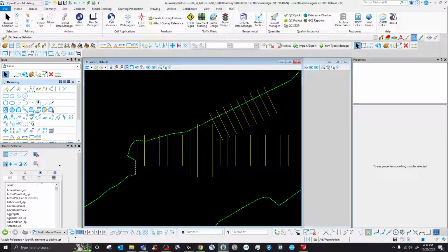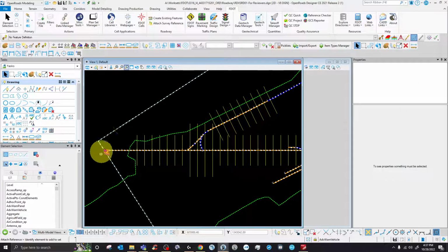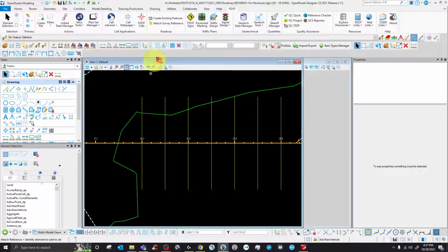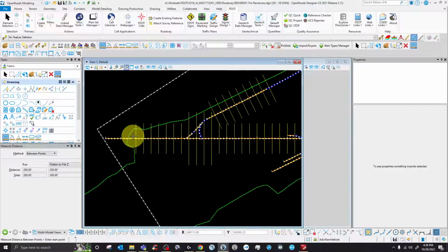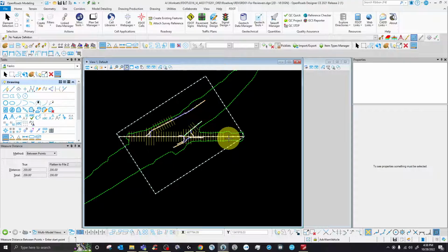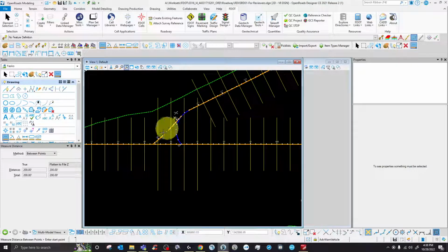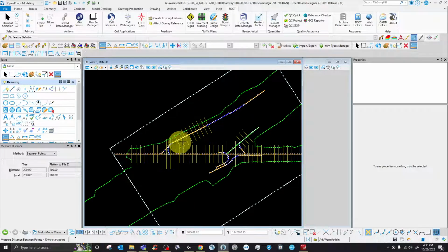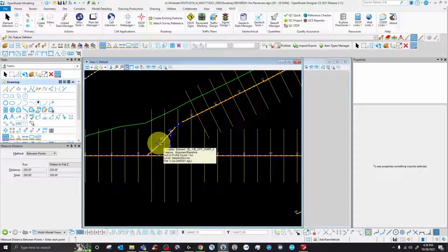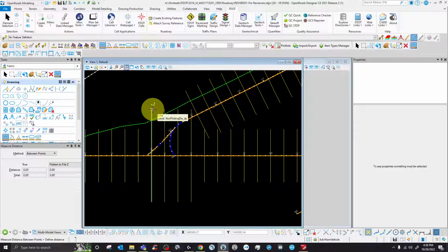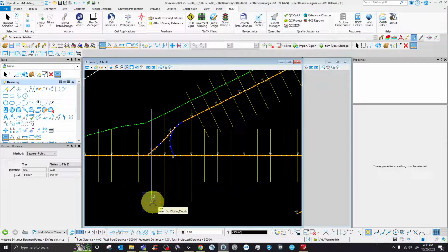So what I was trying to say is I already did this preparation. When I say preparation, I mean I made sure that this is 200 here to cut cross sections, and it's an increment of 50 feet, and I laid it down over the whole thing where we're stopping. Since here we have work for the ramp, I decided, I hope it's gonna be okay, I made these cross sections actually more than 200. I made them 350.